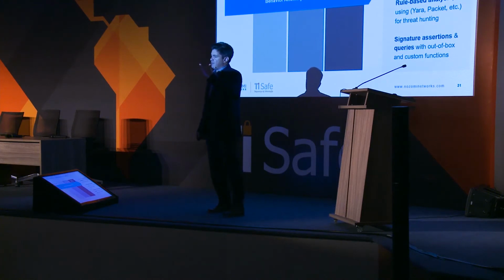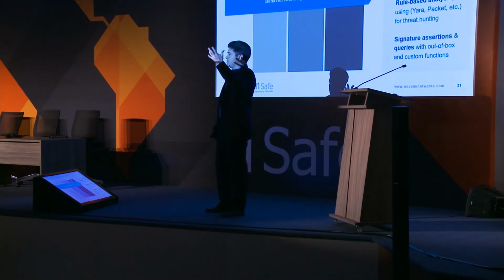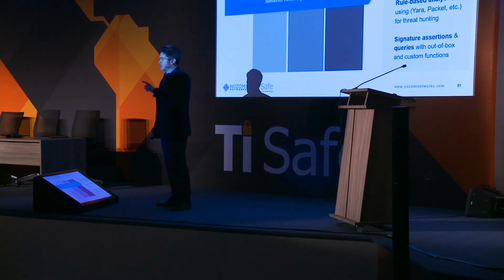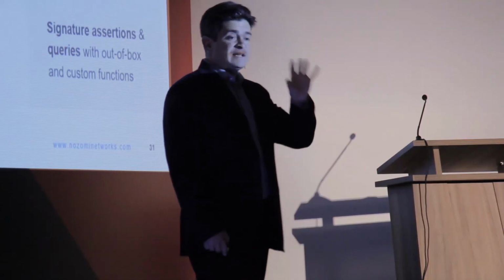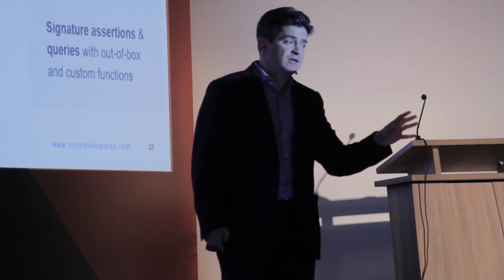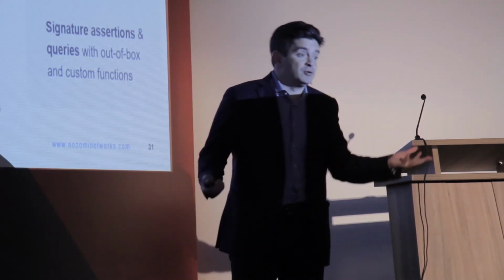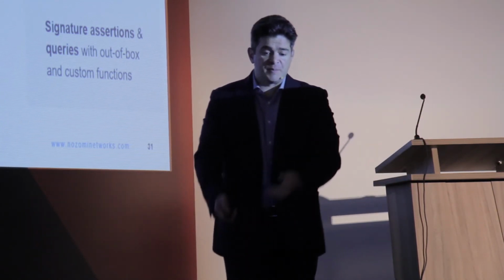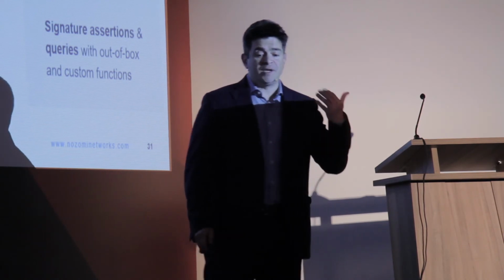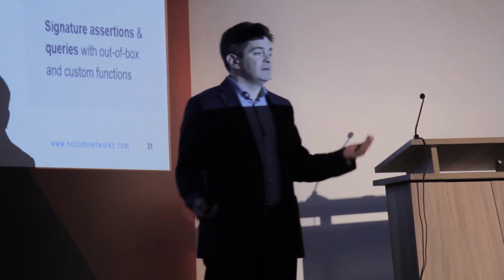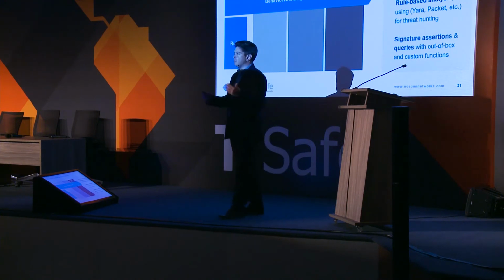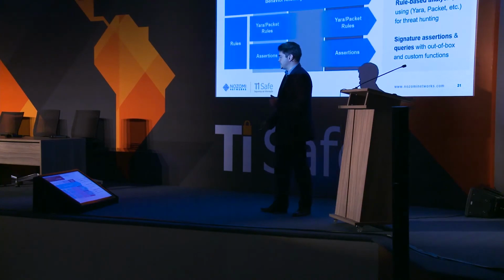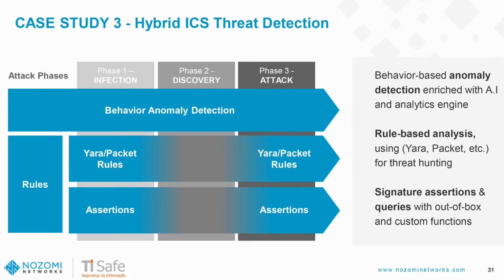But sometimes, if researchers around the world have synthesized an attack, for example, in Destroyer or Black Energy, it would be silly for us not to tell you that this is an attack that has a signature, and by the way, this behavior is associated with that signature. So we are the only solution in the market that combines both behavioral-based anomaly detection with signature-based anomaly detection. So we use YARA rules, packet rules, and we also allow assertions.